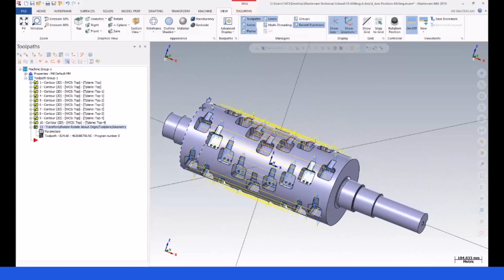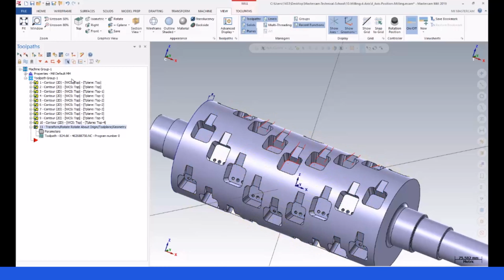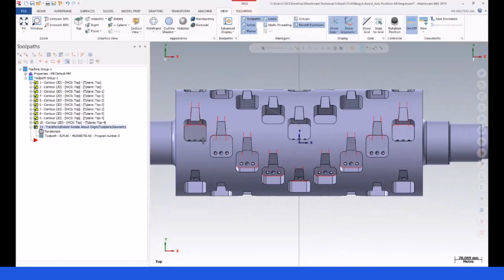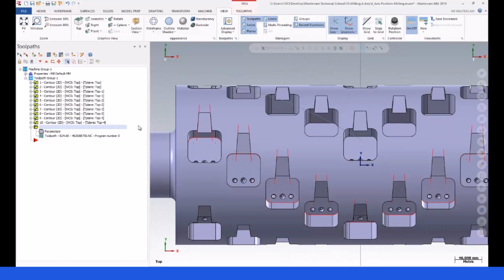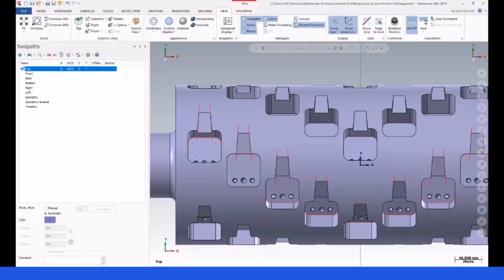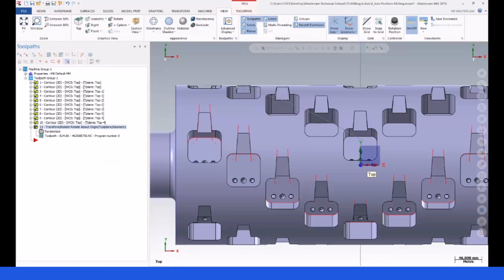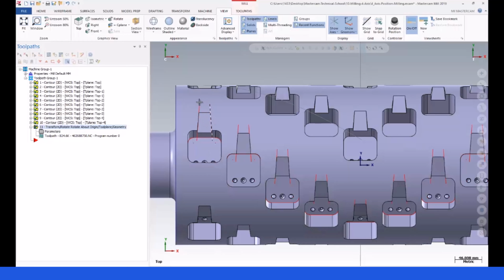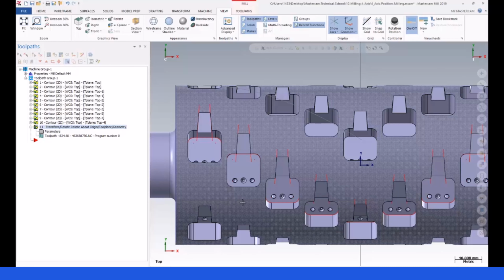That's enough. In that case, maybe you also consider that perspective. That is my perspective. You can rotate your product, and when you click on the top view, you can see that geometry. After that, when creating your toolpath according to that position, you can rotate and transform to get that toolpath.